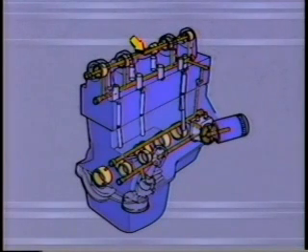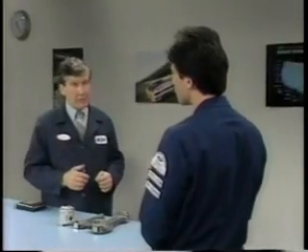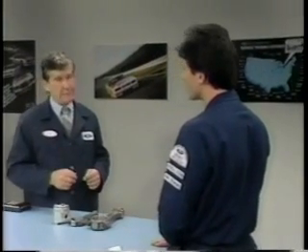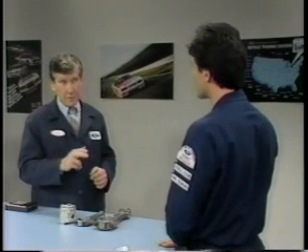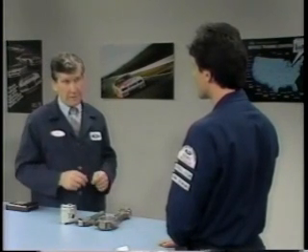Also note that the camshaft is hollow, and each individual camshaft lobe is pressure-fed oil. The other components, such as the valve components, are lubricated by spray and dripping oil. A point to note is that not all overhead cam engines utilize the hollow camshaft as an oil gallery. In these other applications, the camshaft lobes would be lubricated by spray or dripping oil.